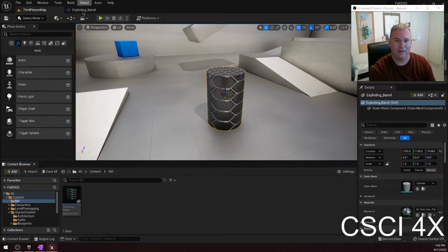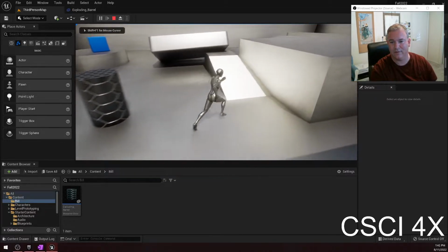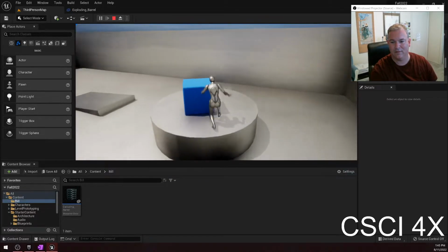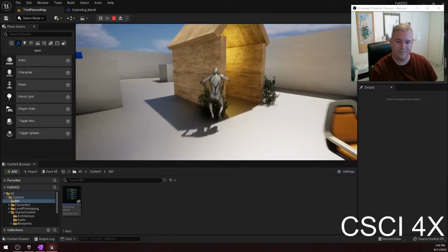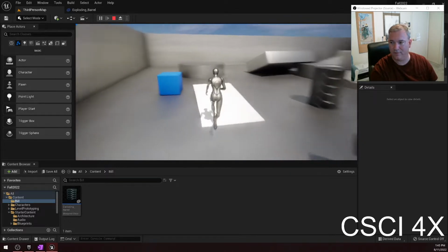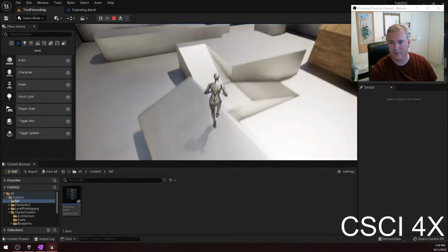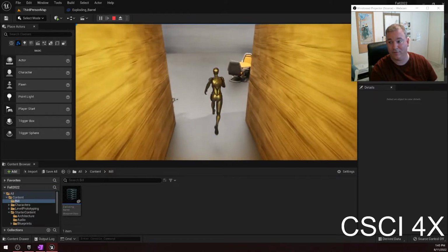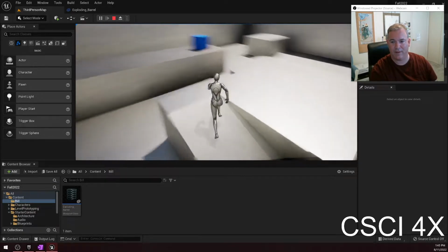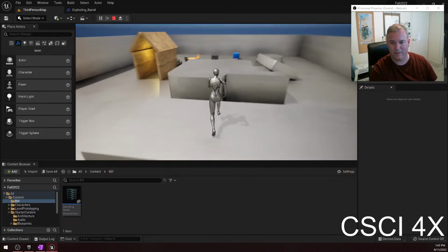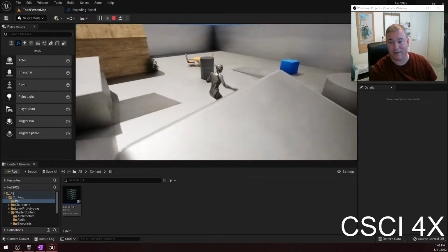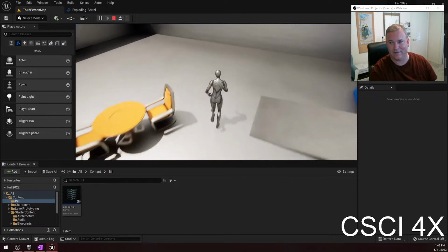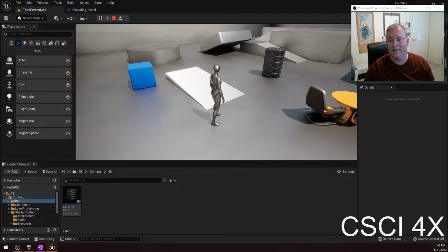So okay, how do you enable your character model again? What do you mean by the character model? The little mannequin here? It's just the default. You should have picked the third-person template for Unreal Engine 5. You are in a camera view. Then you probably made the first-person template. So go ahead and quit out of that and make the third-person template. The reason for that is because the first-person template doesn't actually have a body. It's literally a disembodied pair of arms and a gun, and so you can't actually move the camera out and stuff like that.